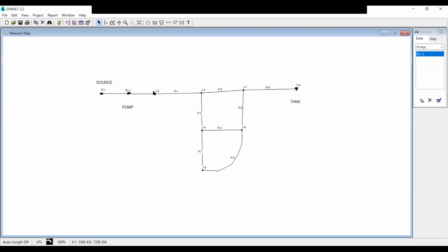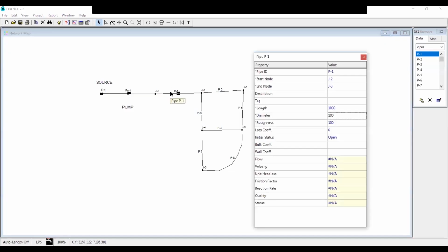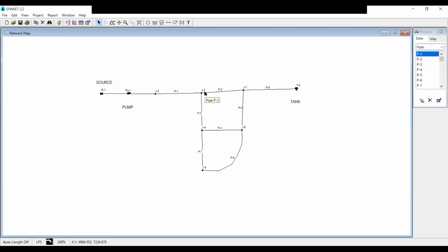You can edit this in your project as well. And give the length to this pipe. So this part has no length. This is just for the pump. Okay, this is an imaginary length. And my real length is here. For example, if it is 5 kilometers, you will enter it here, 5,000. Okay, this is the main idea behind the junctions.